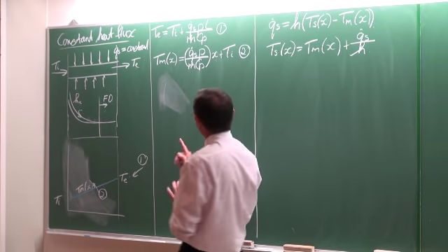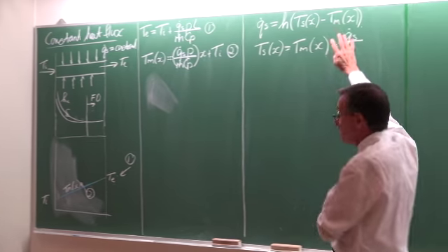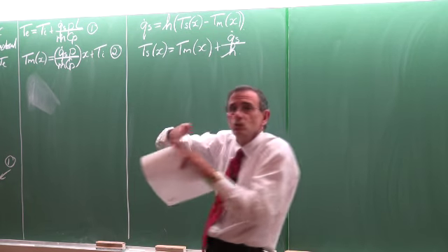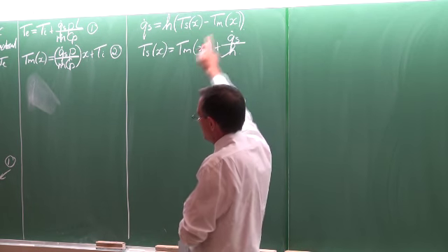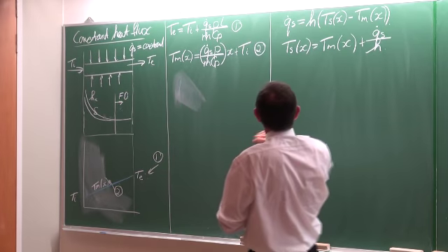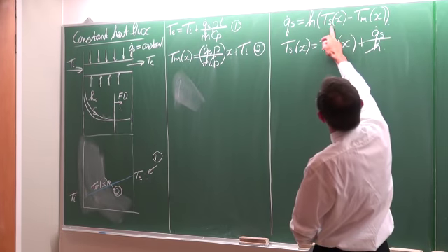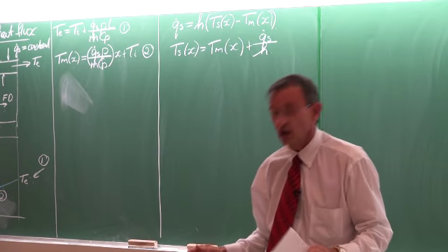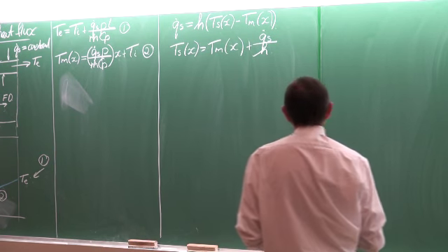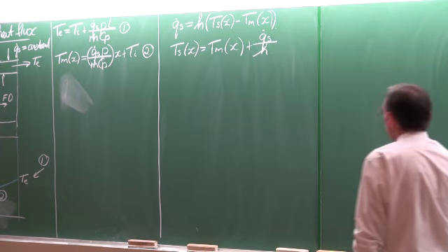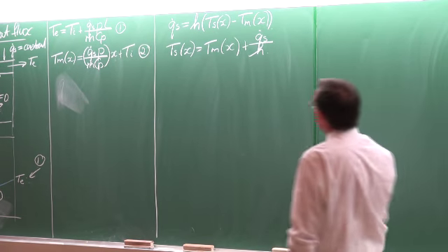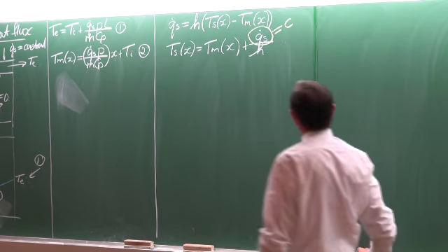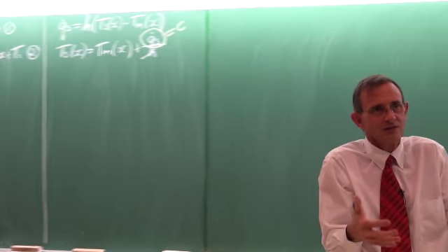Now we want to get the surface temperature. So we've used that equation. The heat flux is equal to the heat transfer coefficient multiplied by the surface temperature, which varies, minus the mean temperature, and we can also see it is not a constant. Okay. So from here we can solve the surface temperature and we can write it like that. And that is where our previous lecture ended. Okay. Now if we look at this equation very critically, then this is a constant. Okay. That is a constant. It's a constant heat flux problem, so that is easy.